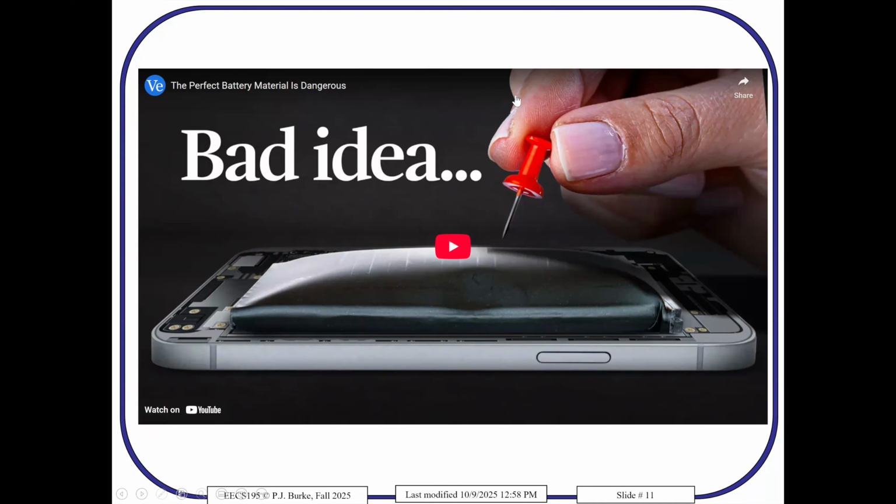But you also short circuit the cathode to the anode, and that drives a lot of current very, very quickly. That current then melts the cathode, the anode, and the electrolyte, and it draws more current, and you have a positive feedback loop. And everybody knows a positive feedback loop is not stable. So you have thermal runaway, and the instantaneous rate of increase in temperature is 100 degrees Celsius per second. You can do the math on that, and it results in a fire.